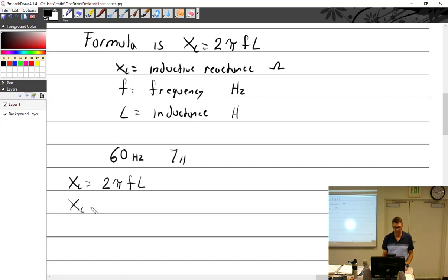So X of L equals 2 times pi times 60 times 7. 2,639 ohms. So X of L equals how much? 2,639. Okay, he's correct.